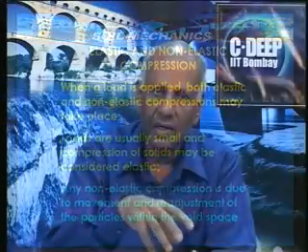It is the non-elastic compression which is important. Non-elastic compression is going to be due to the other causes of the 3 causes that we listed; the non-elastic component is going to be due to the second or the third cause. The second cause was the compression of the water and the air, and the third cause was expulsion of water and readjustment of the particles. So, readjustment of the particles and reduction in the void space in an inelastic manner is what we are interested in.